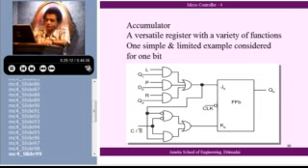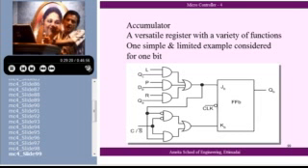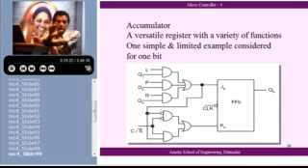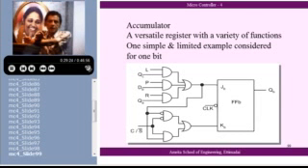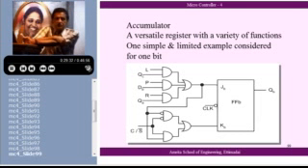An accumulator, you see here, is just a flip-flop. I've shown one stage of an accumulator. I take a flip-flop, if I connect it one way, I can make it part of an up counter. J and K, if I define in one way, I can make it count up. If I change it slightly, I can make it count down. If I change it in another way, I can use it as a shift register with left shift facility.